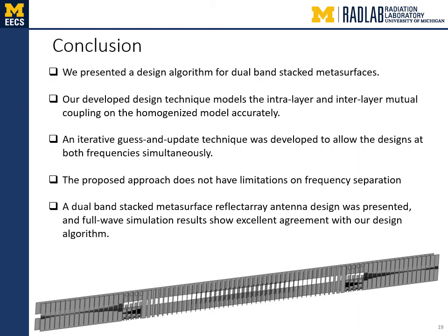In conclusion, we presented a design algorithm for dual-band stacked metasurfaces. Our developed design technique models the intra-layer and inter-layer mutual coupling on a homogenized model accurately. An iterative guess and update technique was developed to allow the designs at both frequencies simultaneously. The proposed approach does not have limitations on the frequency separation. And a dual-band stacked metasurface reflectarray antenna design was presented. Full-wave simulations show excellent agreement with our design algorithm.